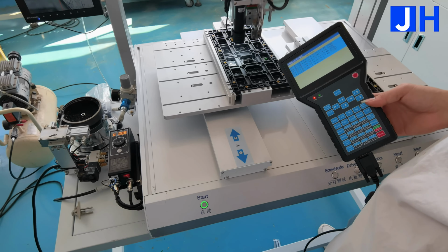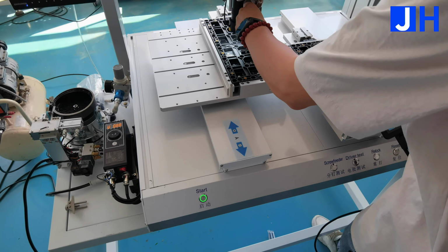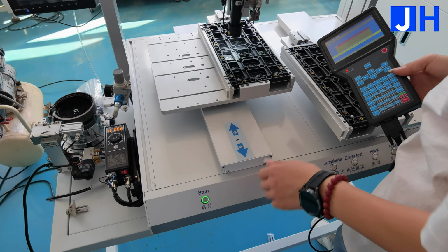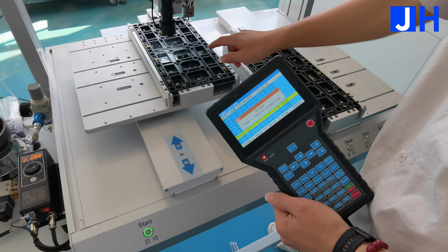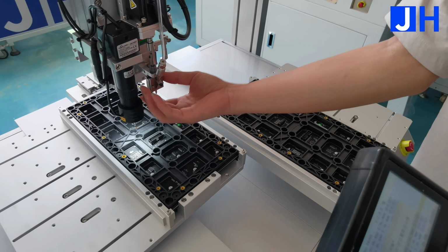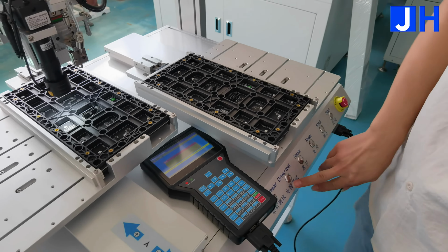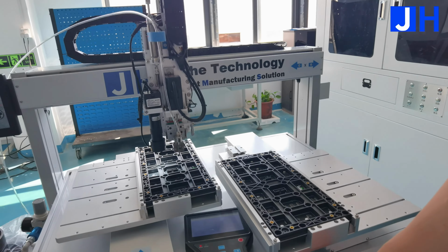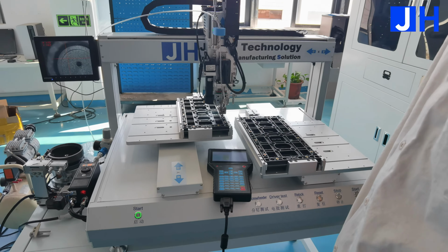The machine detects a slippery screw and issues an alarm. This is because the air is blowing too hard and the screw is blown off course. We remove the screw on the nozzle. If the nozzle does not have a screw, we press the driver test on the machine. Press the driver test button and the machine will start working again.